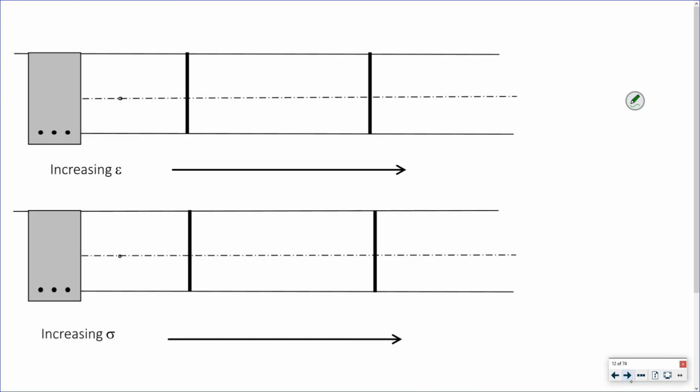So here we have a singly reinforced concrete section, assuming it's subjected to positive bending. Singly reinforced because we only have reinforcement on one side. It's on the tension side, which is the bottom, for positive bending. And we're going to look at the strain versus the stress.